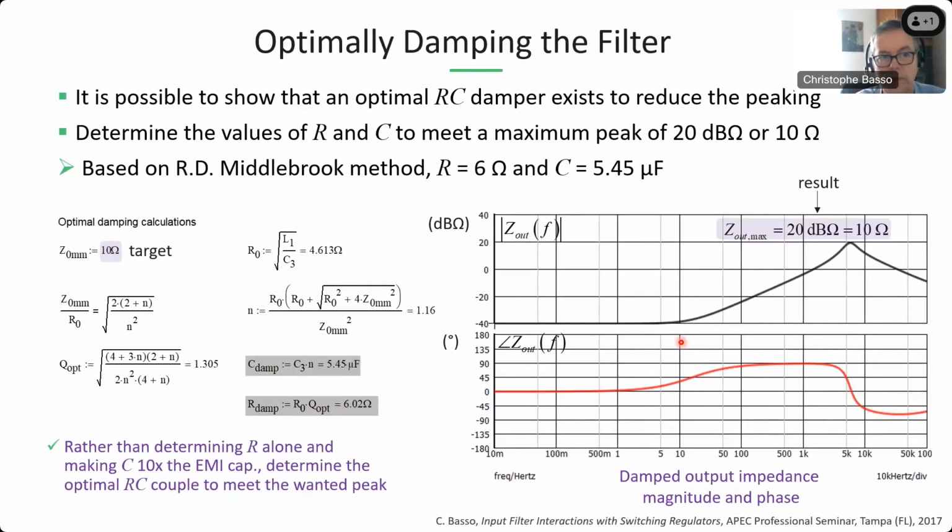You can do something by just damping the filter using, let's say, elements as shown in the literature, or look at the article that was originally published by Dr. Middlebrook in 1976, if I remember well. You have the link in the previous slides, and determine the exact damping elements for bringing the Q, the peaking here, to a value which is far away from the input impedance.